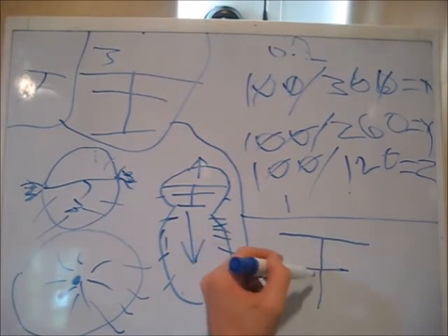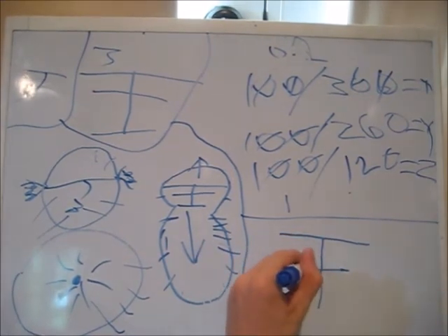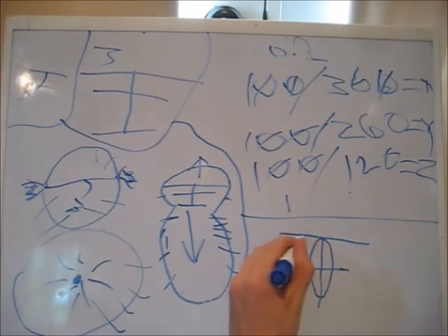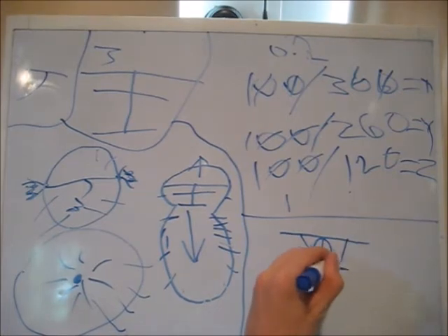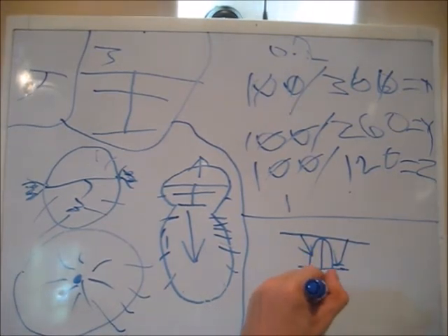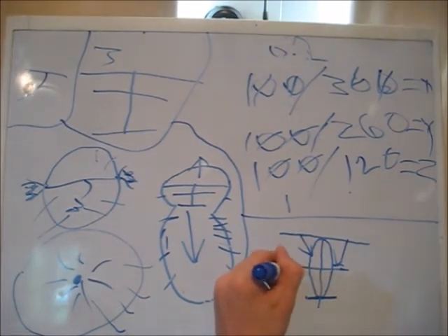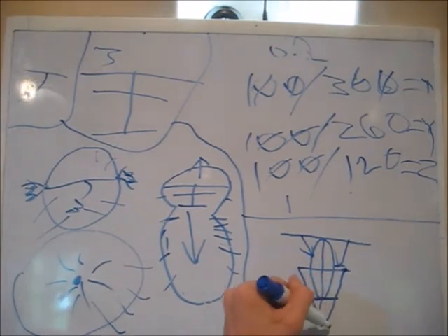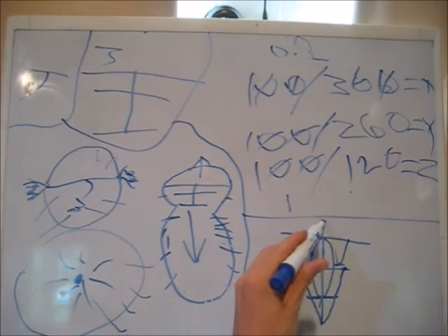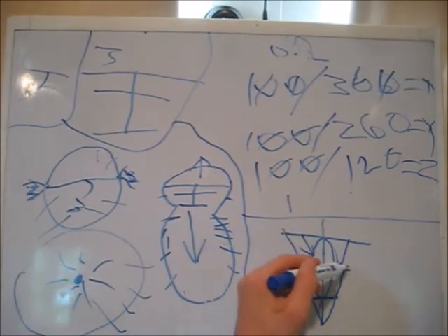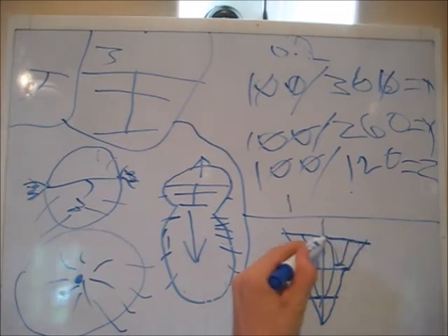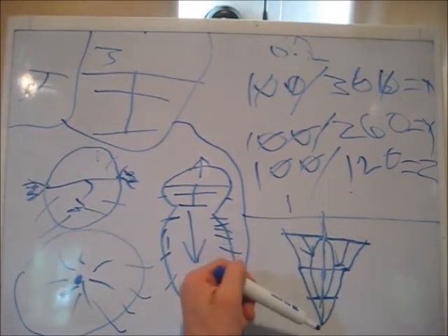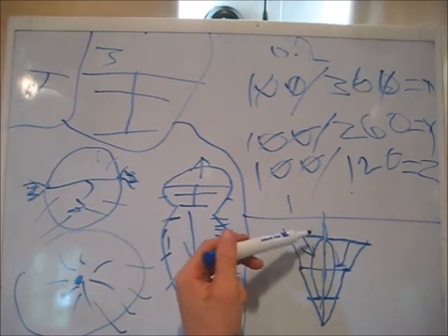This acts as a reflector, and when this radiates in that standard figure 8 pattern that we're talking about, that signal is getting shot back forward. So it's sending that signal back up. Up here, there's a shorter element, and this takes the signal and draws it out into the arrow that it is going to be radiating on. So you can look at your beam antenna as a big arrow, where the boom is the line down the middle, and you can trace these out to get the arrow. So that's sort of the technical how-to of a beam.